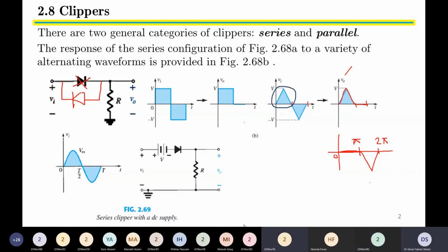And sir, if we connect two diodes in parallel with the opposite direction, will they act as a single wire? Well, this question was dealt with in an earlier lecture also, that if we remove this diode and connect two diodes like so, then one diode will be forward biased and the second diode will be reverse biased.